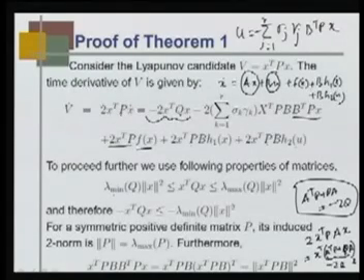The lower bound is lambda minimum, that means the minimum eigenvalue of Q, times X norm square, and the upper bound is lambda max of Q times norm square, because Q and P are symmetric matrices, hence the maximum singular value is the same as the maximum eigenvalue. Therefore, minus X transpose Q X is less than or equal to minus lambda min Q X norm square.